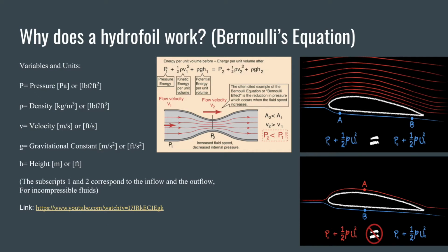When we do this, we must take into consideration that Bernoulli's equation can only be used when a molecule flows along the same streamline and not across streamlines. In this equation, we are working in units of pressure and comparing the pressure at the front of the hydrofoil to the back along the same streamline, as well as the kinetic energy associated with the velocity. We can neglect any height because delta z, or the change in height, is minimal or close to zero. Bernoulli's principle or equation is of vital importance in regards to how a hydrofoil works. The general summation would be that it evaluates the conservation of energy from one instance to another for a fluid.